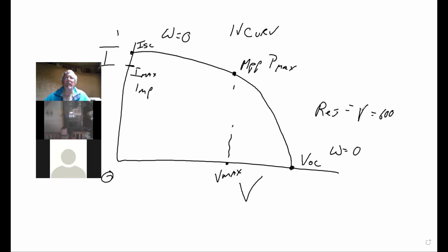So when we're designing for voltage, we're going to use the VOC because that's the theoretical worst case scenario. For amperage, for the wire size, we're going to do this, but the operating is going to be the Vmax and the Imax.